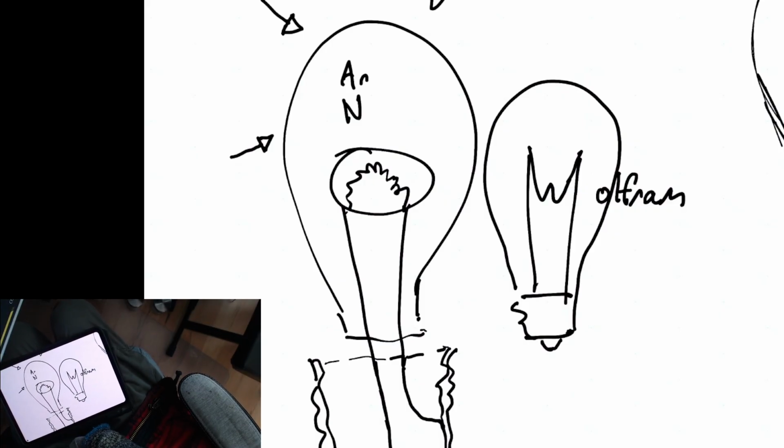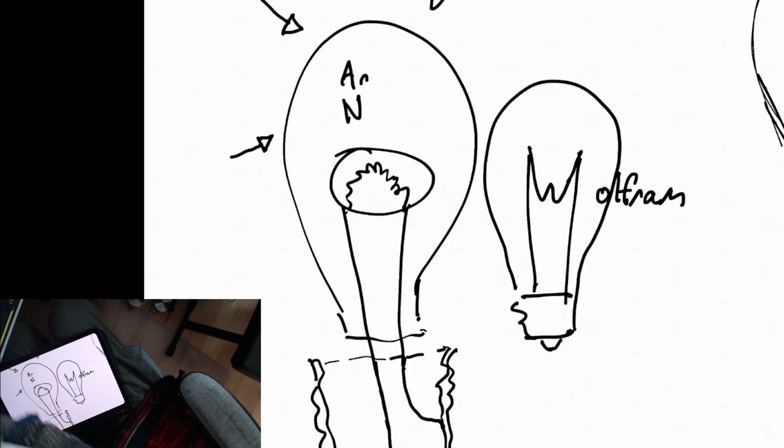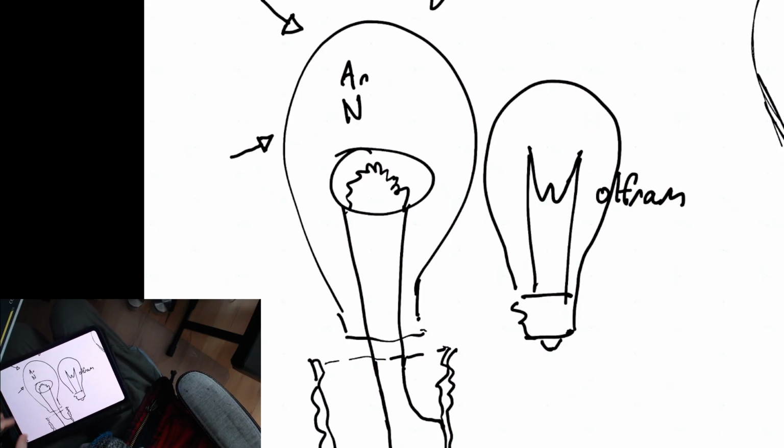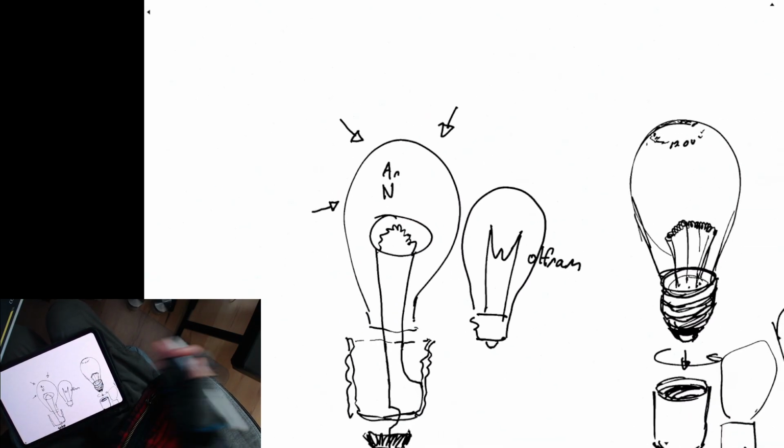Prior to shipping the light bulb out, they'll test the light bulb. They actually turn the thing on. And during the testing phase, when the light bulb turns on, the getter burns and it gets the oxygen. It gets any remaining oxygen out of the bulb after they purged it. So the getter gets all the rest of the oxygen, and that way there's no more oxygen anymore. It's all been consumed by the getter.